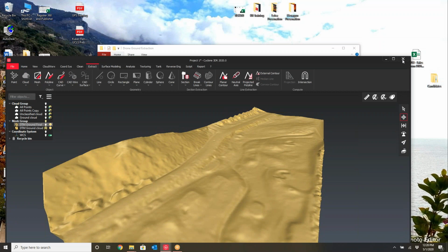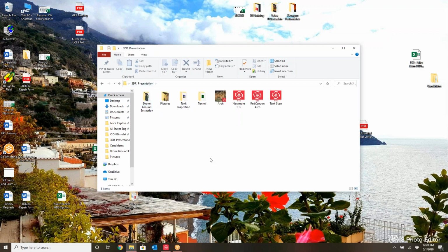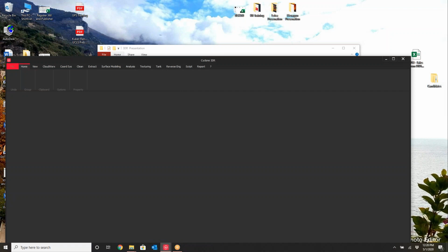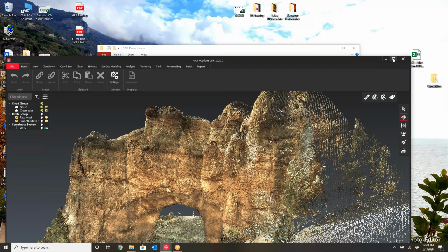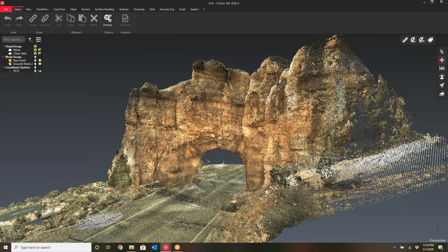Go ahead and close that. Question, as you get that other part going, how does this relate to, let's say, RTC data? That's fantastic, by the way. With RTC data, let's say you collected a bunch of RTC data, you brought it into Register 360, managed your data edits, output an LGS file from Register 360, and then into here. It's the same process, a little bit different. I'm actually very glad you brought that up. That is something I wanted to cover, and I think I can do it.